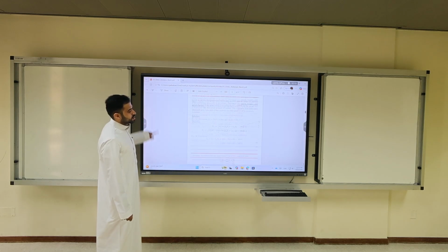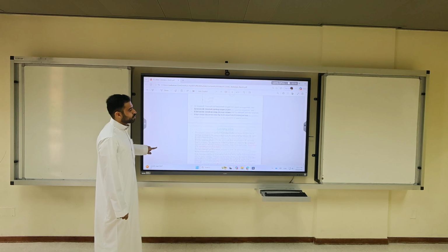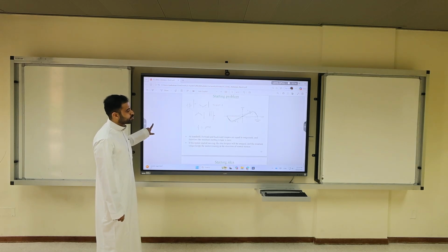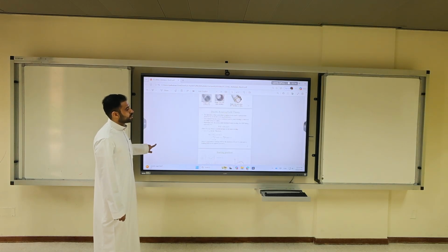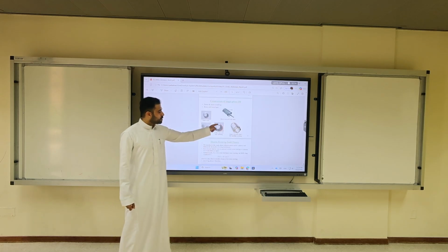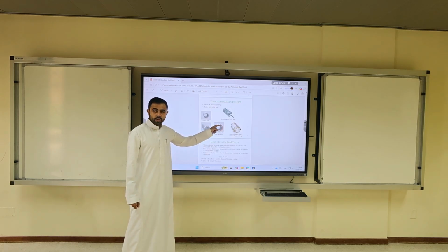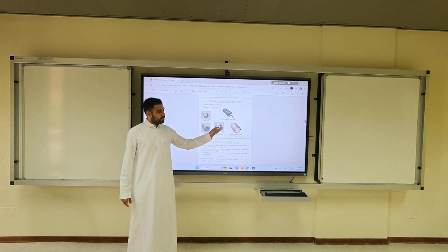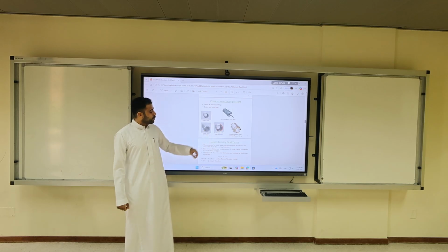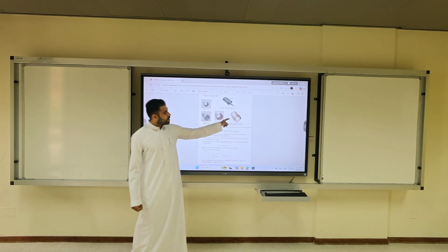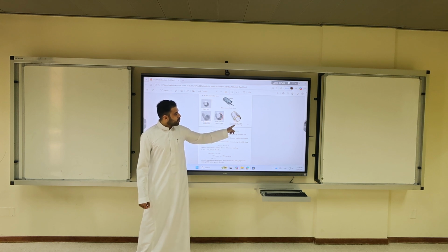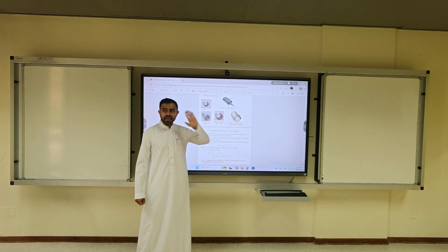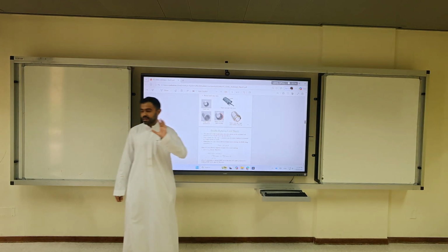So in the previous lecture, 38.5, what was the main argument? The main problem we have: if you have just one phase, one coil, it will not rotate. It will not self-start. And if you spin it, it will be full of ripples. So they added an auxiliary winding to resemble a fake second phase. It's not a second phase, it's a fake second phase.